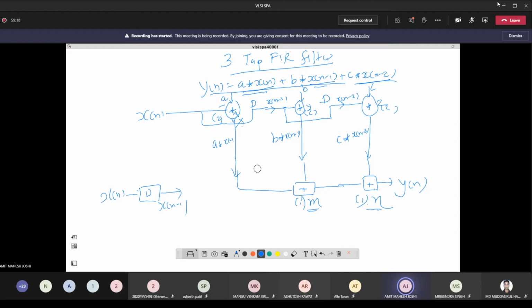Okay, just to replace this in a DFG graph, because for a DFG it is simply x, y, z nodes. For you, you know that x is a multiplier, y is a multiplier, z is a multiplier, but that understanding is not required when you go for DFG based optimization. So now I want to apply the retiming concept. For a retiming concept, I need to understand the critical path.